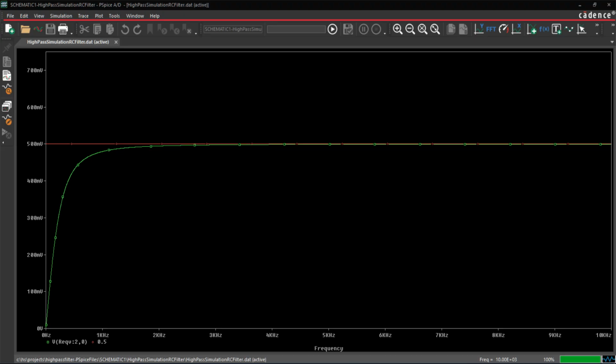Next, the probes measure the amplitude of the output signal. We have positioned probes so that they take a reading from the equivalent resistor, which is analogous to the signal that would appear at the base terminal of our NPN amplifier circuit.